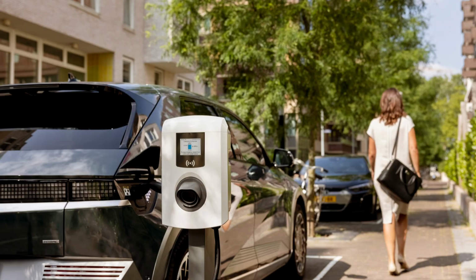If you see a 22 kilowatt charger on a street, this is an AC charger. Unlike the fast chargers, they do not have charging cables, but a plug, and you have to use your own cable that you have in a car. They deliver a maximum power of 22 kilowatts, but the actual power depends on the maximum power of the rectifier in your car. Most cars today, including Tesla Model 3 and my car, have only an 11 kilowatt rectifier. As far as I know, the 22 kilowatt rectifier is only in Renault Zoe, BMW i3, Tesla Model S, and Tesla Model X. Anyway, so at home, I'm limited to 11 kilowatts, which is perfectly fine for me.